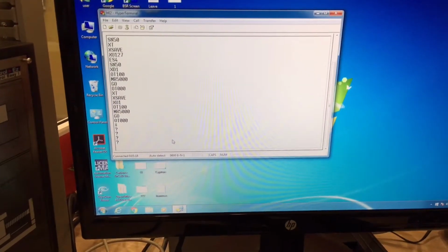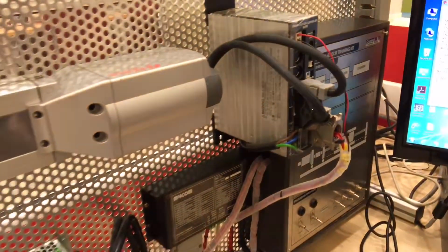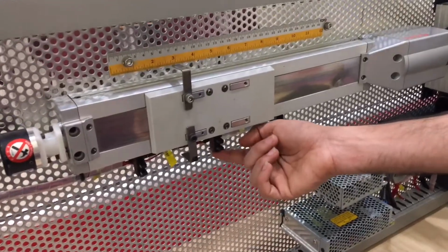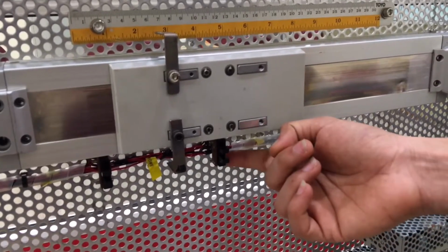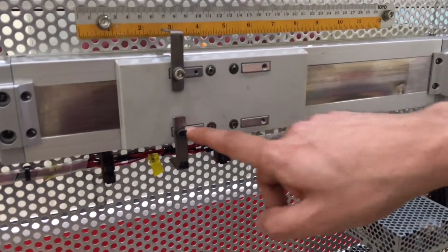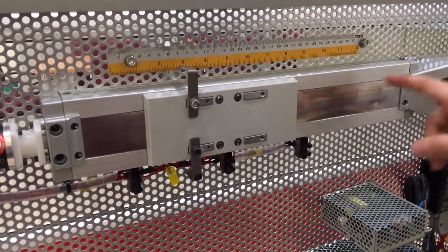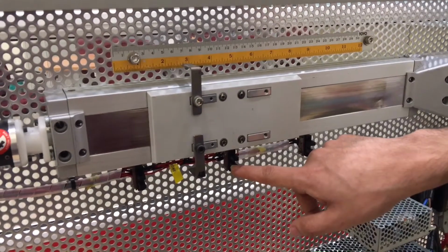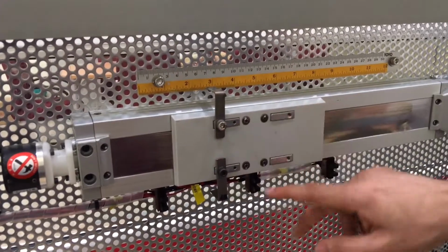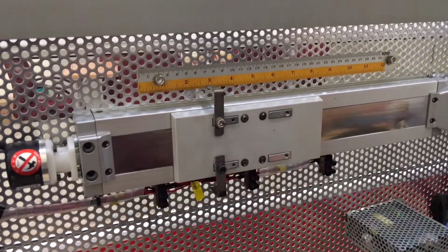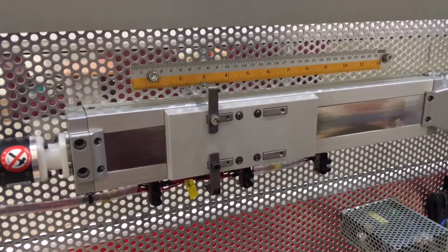We can do home, or perform homing, which takes the machine into the home position. This is the home sensor, forward, reverse. Now this is the home for the program needed for this machine. Wherever it is in this program or in this machine, it has to go back to this place. So this is a simple program you can have to move the machine right into this place, no matter where it is located or currently stopped.